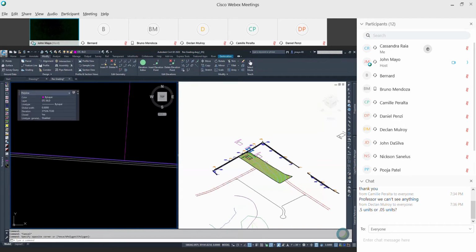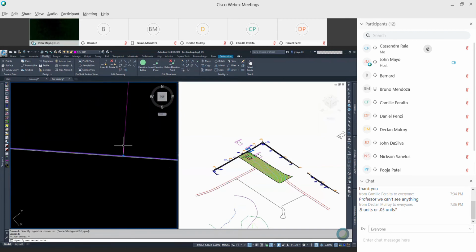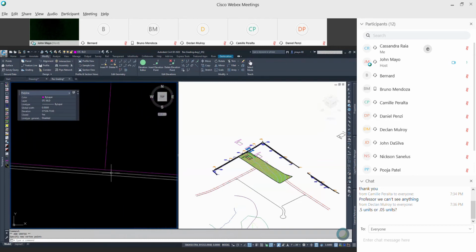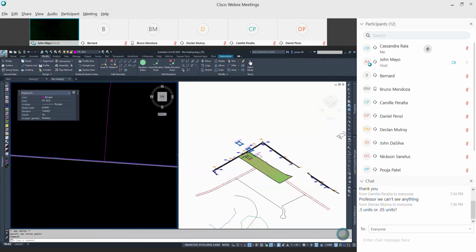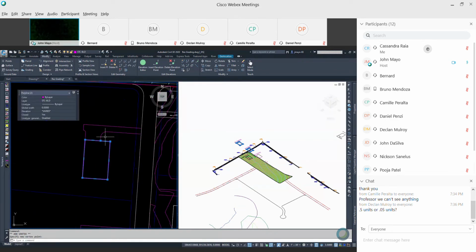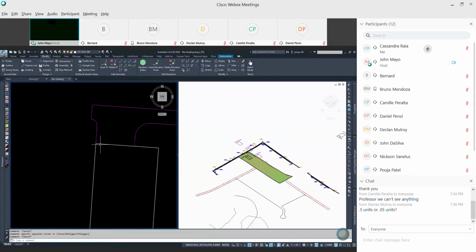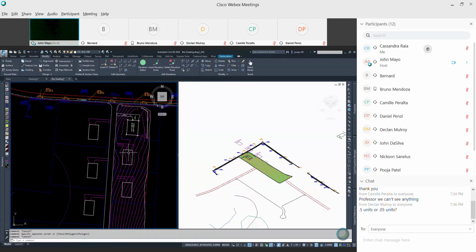grade lines. And if I had you guys do very detailed models that had sidewalks and steps, and all that other stuff, and terraces off the back, you would be doing the same at every intersecting polyline. So we have 2 polylines intersecting, I add a vertex. We have 2 polylines intersecting, I add a vertex. These 2 over here are lined up, the vertex is already there. That's your starting point, right?